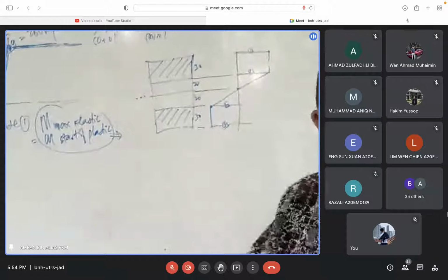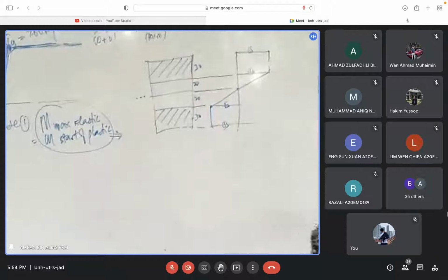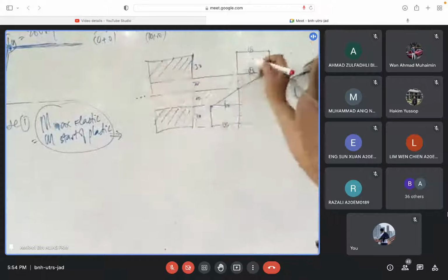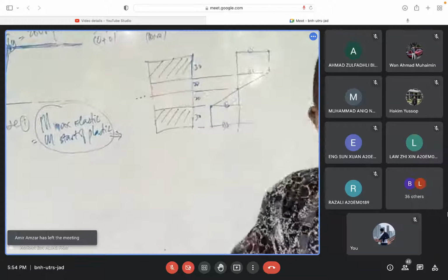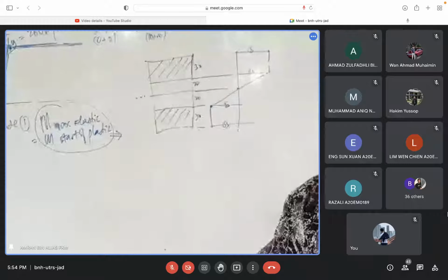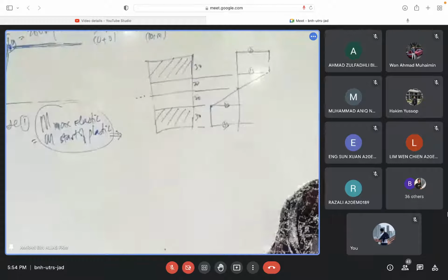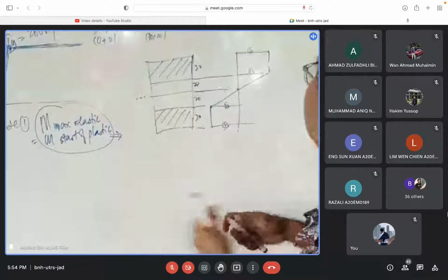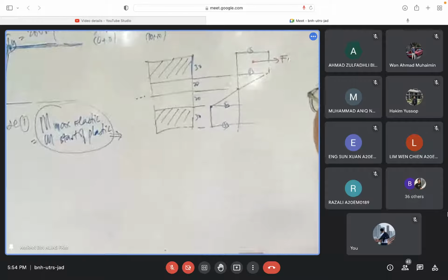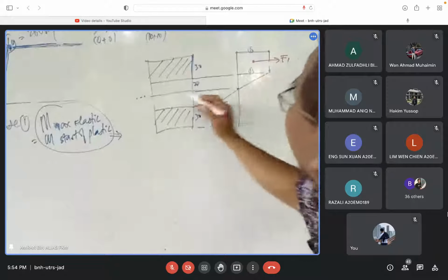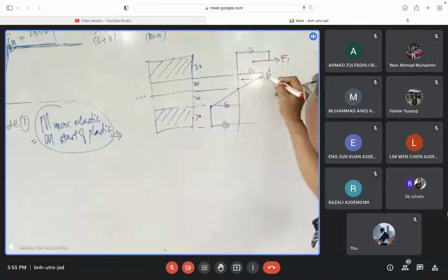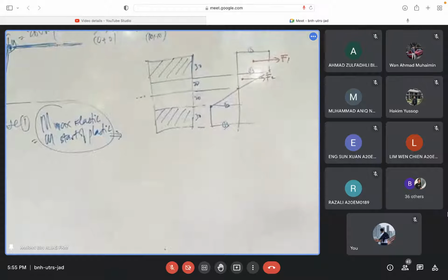So from that diagram, draw the force arrow. So this stress here will act on that area, will become a force there. There will be another force there. Here. There must be a force here, F1. And then the triangle here, act on that area, there must be another force there, on the centroid of that, F2.